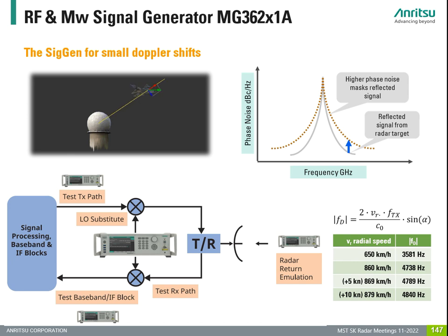Our example shows some typical Doppler shifts calculations for a radar that is operating at 2795 MHz. A radial speed difference of approximately 5 knots is resulting in a Doppler shift of just 51 Hz. This is very small compared to 2795 MHz.